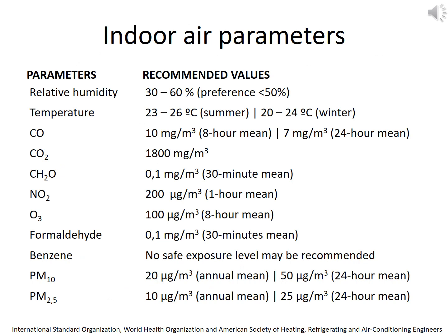For air quality measurement, numerous indices have been proposed. The first index was the Pollutant Standard Index, which was modified and replaced by the Air Quality Index, both of which were developed and introduced by the United States Environmental Protection Agency. The Daily Pollutant Standard Index is determined by the highest value of one of the five main pollutants: sulfur dioxide, ozone, nitrogen dioxide, carbon monoxide, and particles smaller than 10 micrometers.